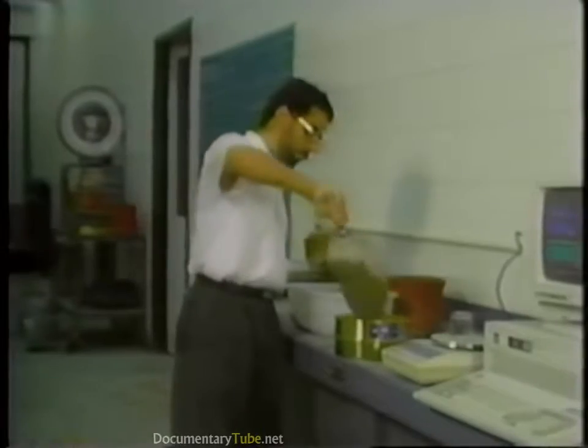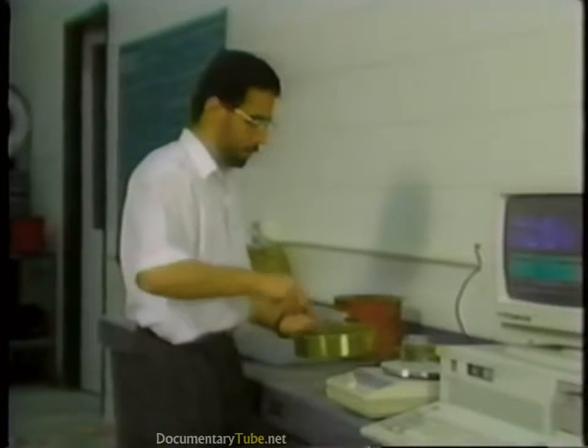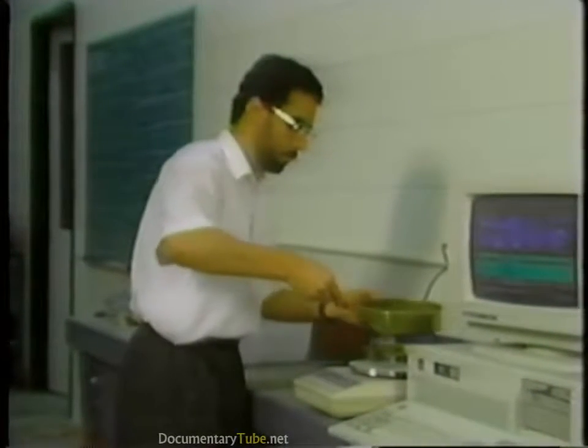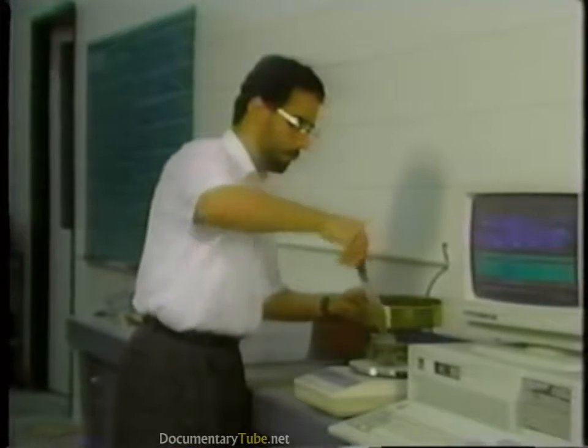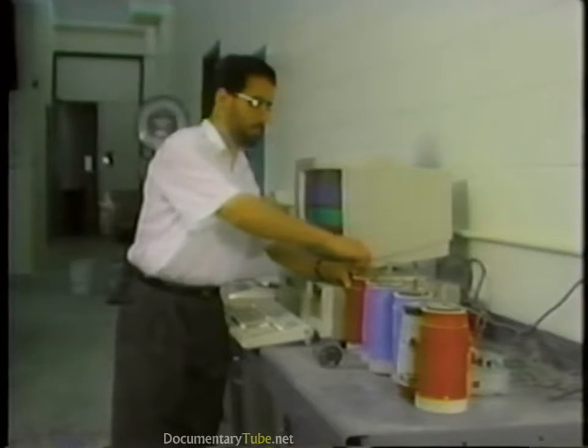Hydration is an exothermic process which generates heat through chemical reactions. The process of hydration can be easily followed by monitoring the production of heat that accompanies the reactions. This is done by sieving mortar from a batch of concrete and weighing it into a bottle which is placed into an insulated container.